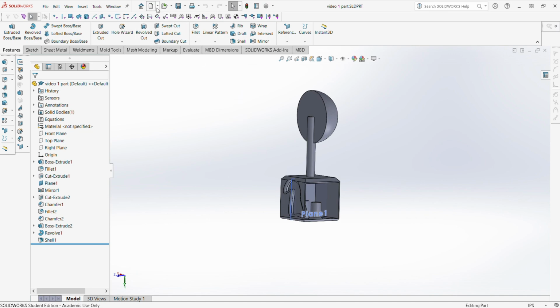So I realized in the first clip, and I have not since figured out how to fix that, that you can't see my drop down menus, so we will sort that out at a later date, but for now I'll just explain it. So you're going to go drop down New and then Make Drawing from Part/Assembly. You're going to want to click that, and then this box is going to pop up right here, it says Drawing. It's going to be highlighted. Hit OK.